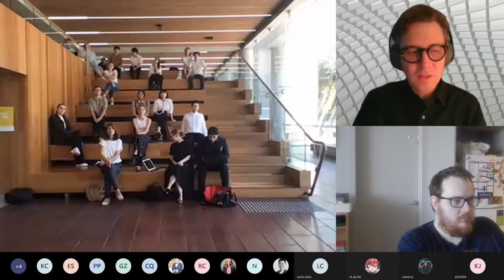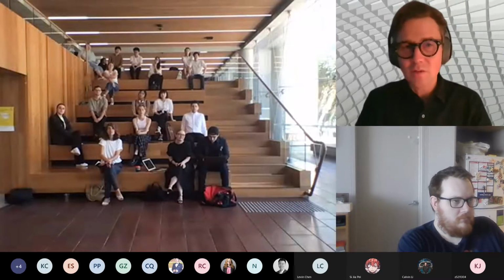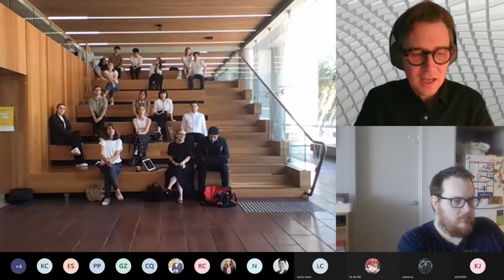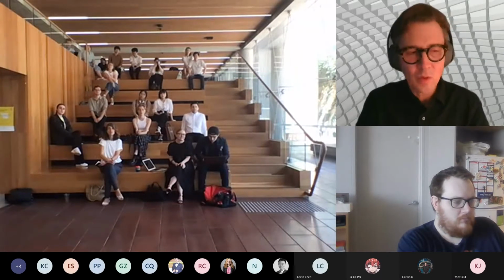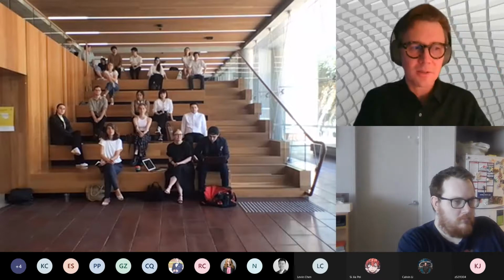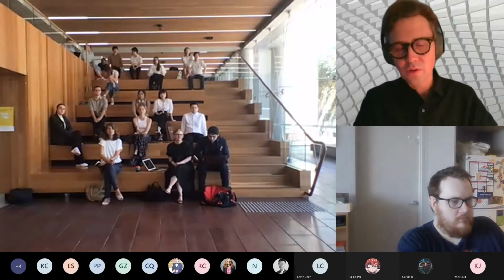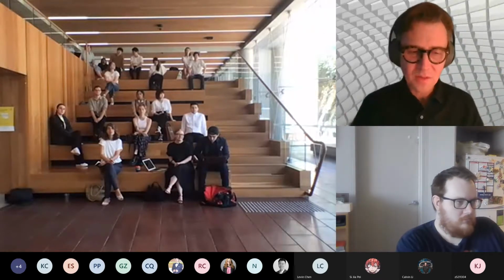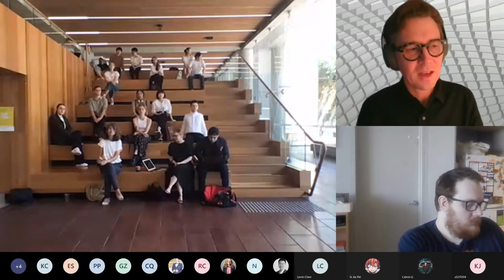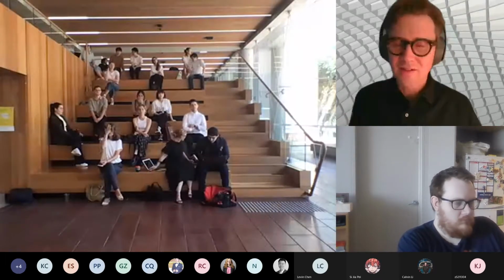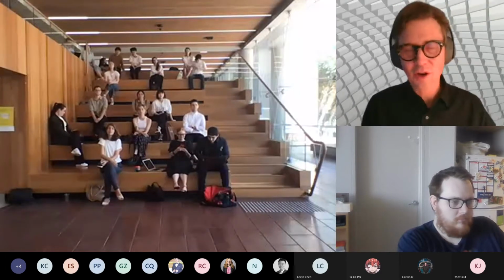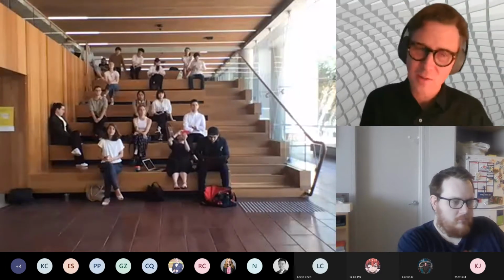This is an exercise that I do with the students that take my acoustics course with me. What we do basically is model or measure a room dimensionally, and use calculation tools to predict the reverb time. Then we build a virtual model of the room and use something like Pachyderm or Odeon to simulate the performance of the reverb time.